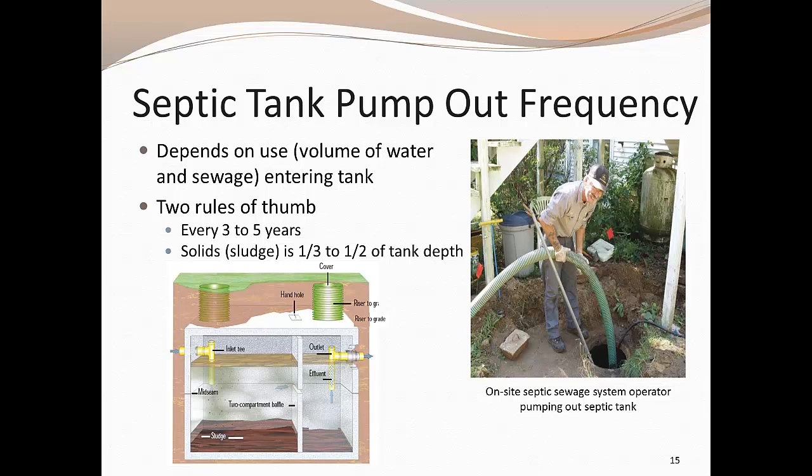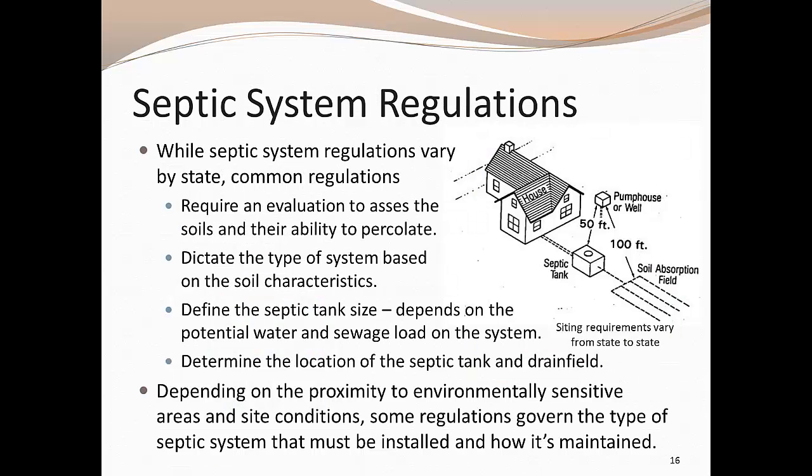Regular septic system maintenance is needed. This is the only way to ensure proper operation and prevent water supply contamination from effluent. A typical septic system inspection will involve locating the system, uncovering access holes, checking for signs of plumbing backup, measuring sludge and scum levels, identifying leaks, examining mechanical components, and pumping the tank if necessary.